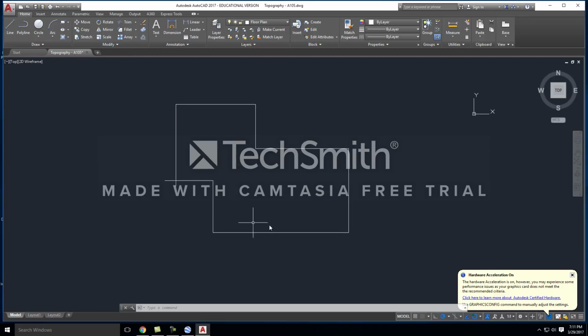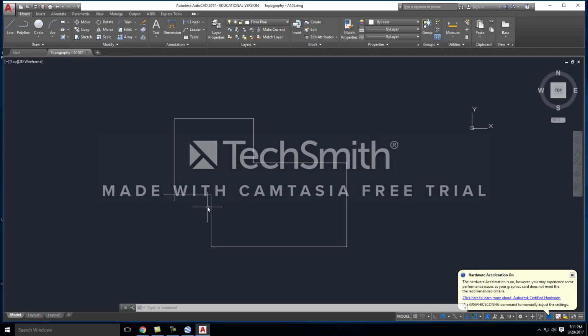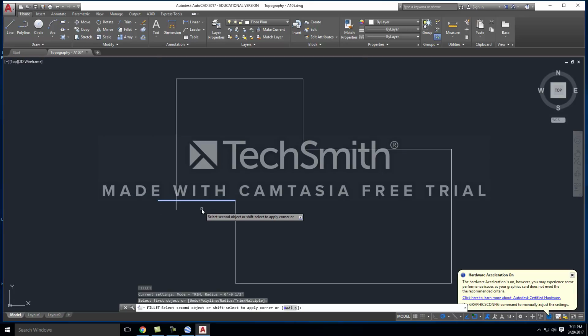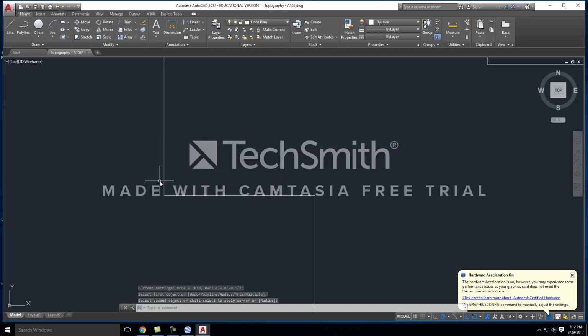So if I hover over, we'll just say this is the outline of my cabin. If you type in F, the shortcut for fillet, and I hit enter, the first thing it says is select first object, okay? The first object I'm going to select is my first line, and then it's going to say select the second object, which will be my second line, okay? Notice when I hover my mouse over that second line, it's showing you how that join is going to happen. So it's going to create a nice perfect 90-degree arc, okay? I'm going to select that second line, and you'll notice that it gave me a nice clean corner, okay?